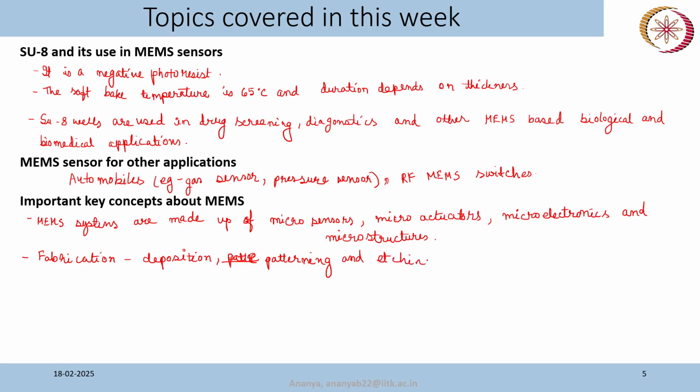as I have given you some examples, that multiple steps of lithography are required. Okay. Another key point was that chemical etching is more popular because of the higher etching rate. I mentioned earlier also that there are chemical etching techniques and physical etching techniques. Chemical etching is wet etching, physical etching is dry etching.